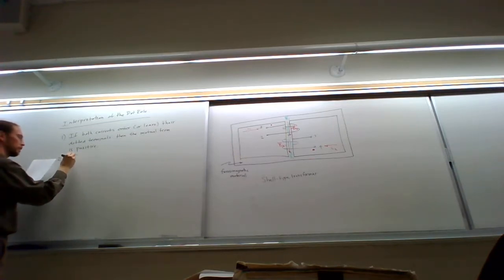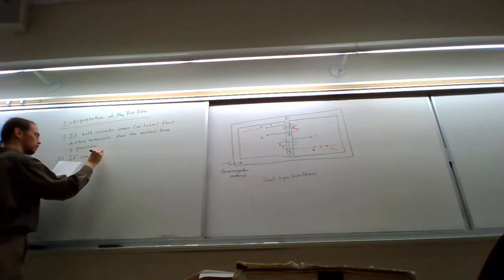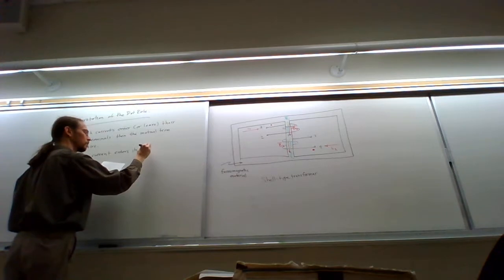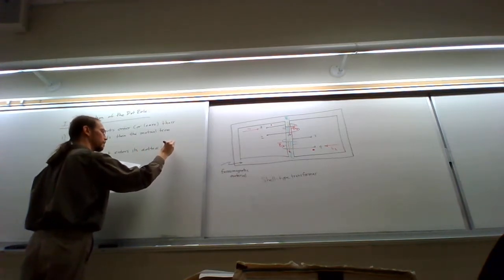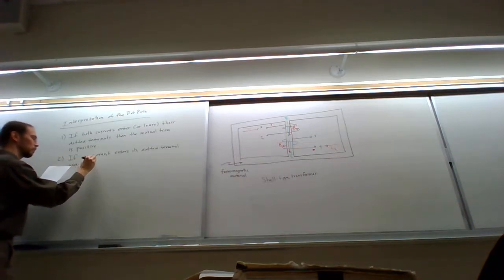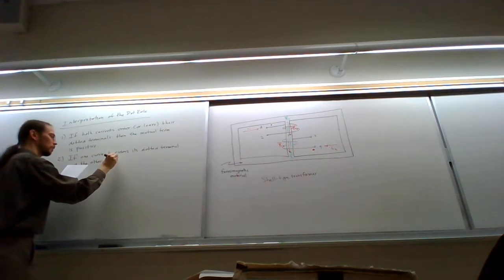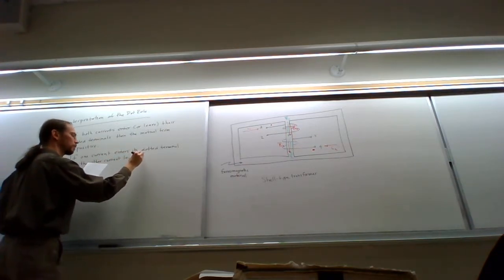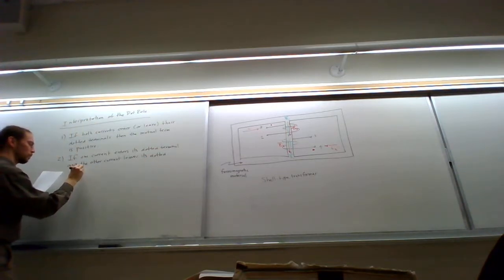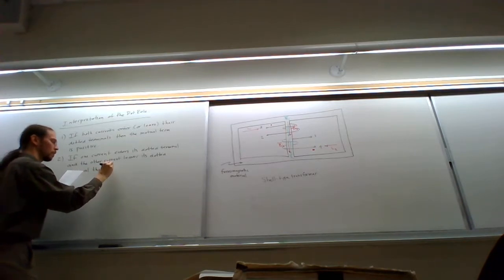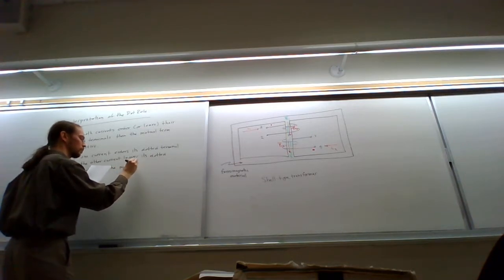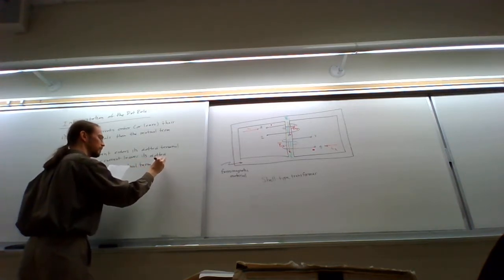Conversely, if one current enters its dotted terminal, and the other current leaves its dotted terminal, then the mutual term is negative.